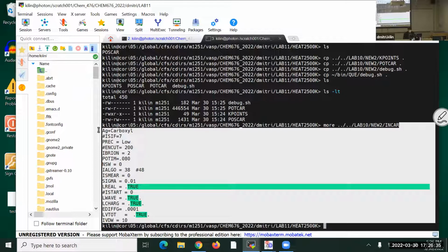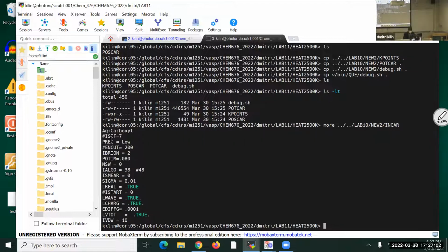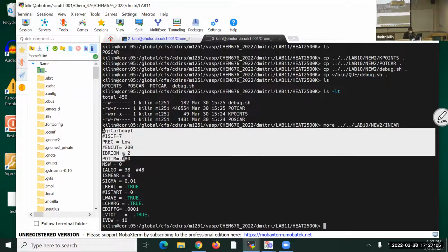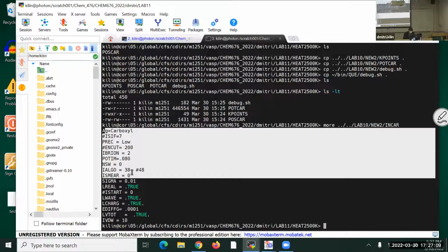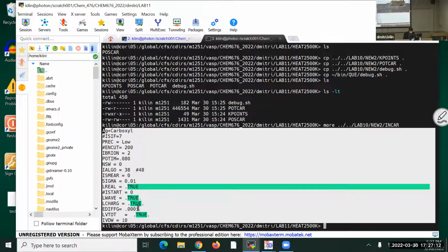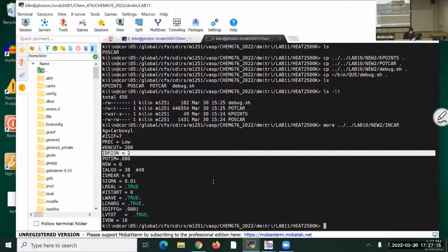And if you really want to become professional, you just learn and then get an idea how to modify each little thing. The difference of VASP from Gaussian is that Gaussian is like automatic transmission, and VASP is like manual transmission. You control all things, and it's too many details to control. But here we are using pre-made templates of the INCAR just to save time in the lab. So the one we were using here was used for either geometry optimization or single point, and we can see like this IBRION 1 and there were several other things.